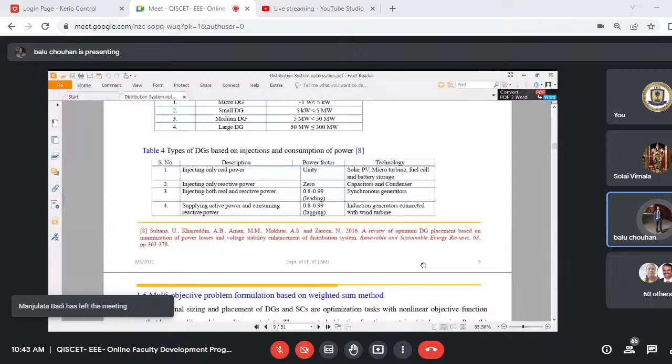But in the load flow studies, we have a random component, so each iteration we get different values. We have to run 100 iterations, and we get 100 different values. But which value is optimal? It is very difficult to find the optimal values, meaning the optimal place, optimal size, real power loss, reactive power loss, voltage stability index, as well as the voltage profile, meaning total voltage deviation. It is very difficult to find which iteration gives the better value. It is the difficult part in the load flow studies.